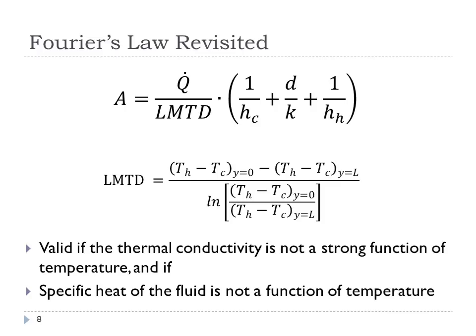So what I want you to imagine is that there are 3 resistors in series, just like in the electrical resistor case, where you've got a voltage, 3 resistors, and then ground. In this case, ground can be thought of as the temperature on the cold side, the voltage is the temperature on the hot side, and we have 3 resistors.